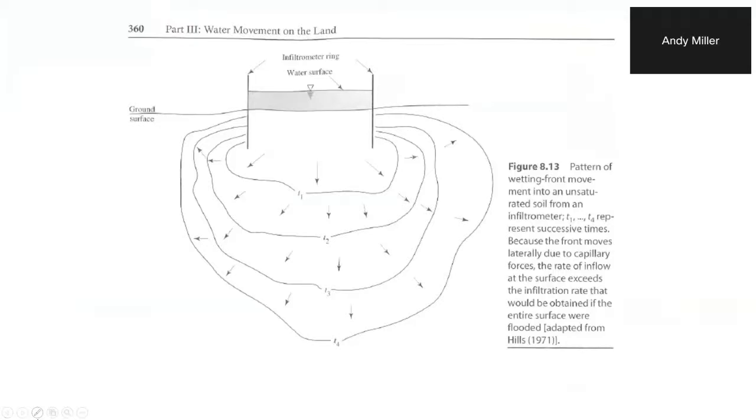Okay, well, these are not actually equipotential lines. These are basically, if you think of the wetting front, time 1, time 2, time 3, and time 4. Although the flow does go perpendicular to equipotential lines, there are equipotential lines in there somewhere. But the main thing is, why is it spreading out this way? We talked about the one-dimensional Richards equation, and we talked only about the vertical dimension, right? So what? Yes, Dan. Maybe the porosity of the ground, or what the material is made of.